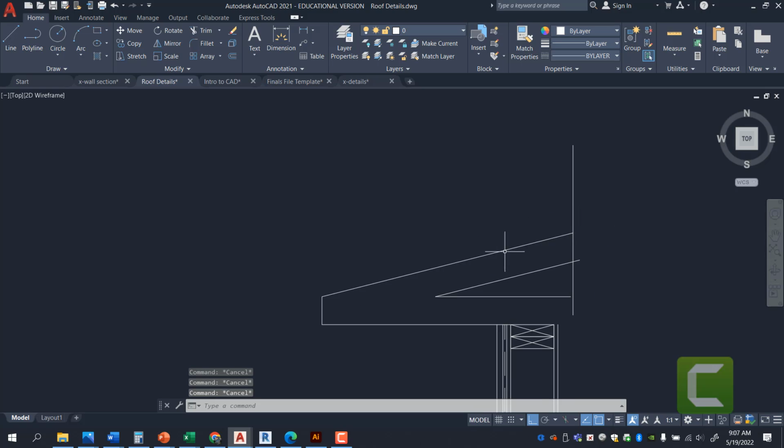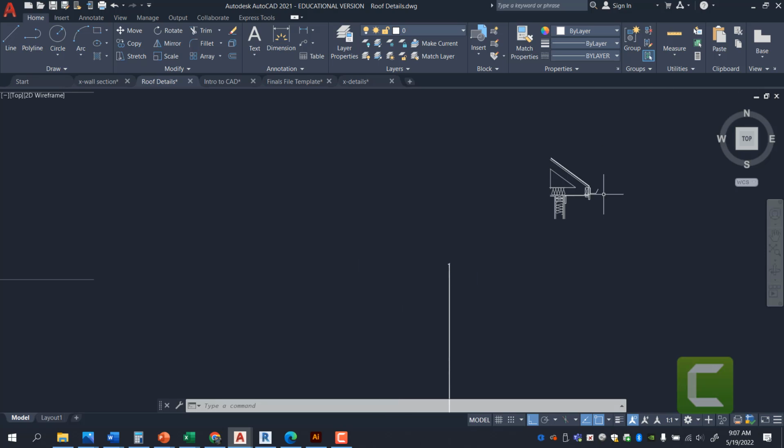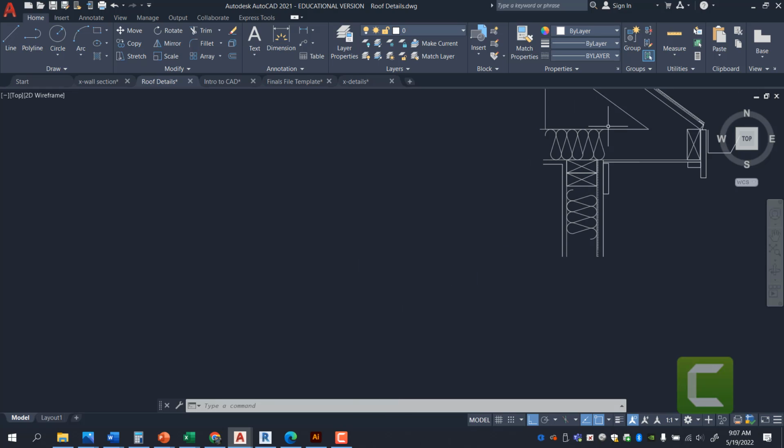Now, on top of your truss, you end up, so the insulation requirements, as you can see in my drawing here, you're supposed to be pretty much insulating up to R38, which is the current code right now, and R13 minimum requirement for your walls.